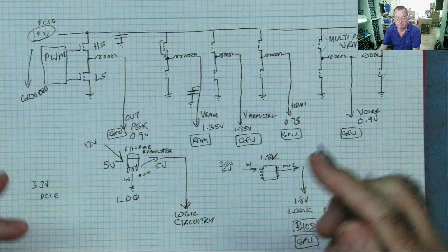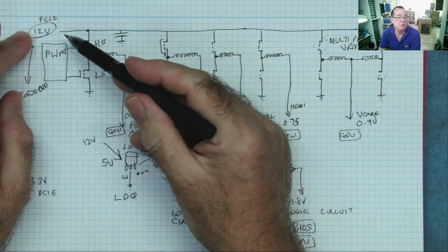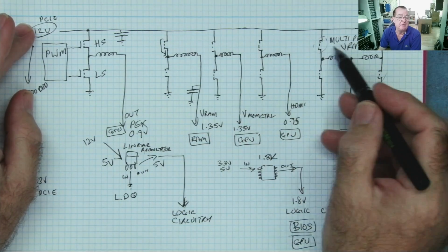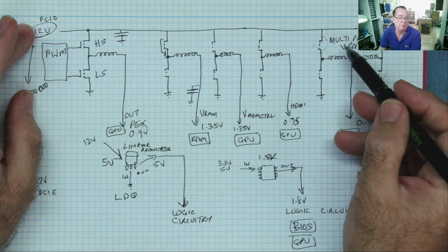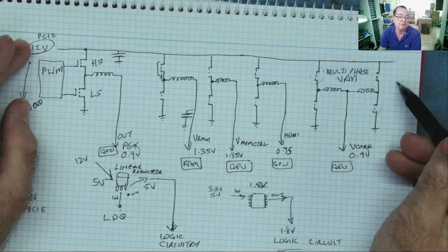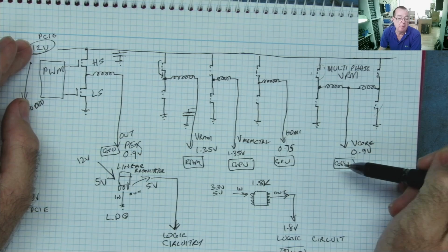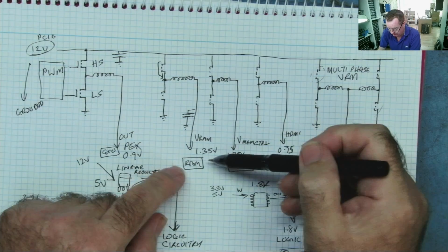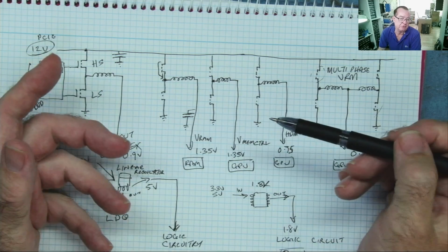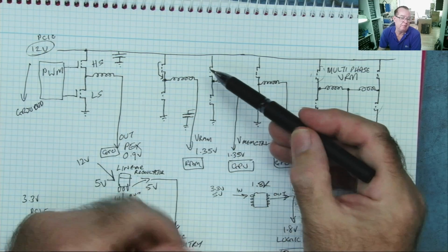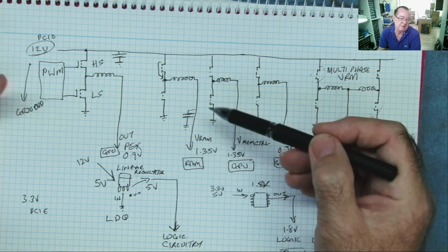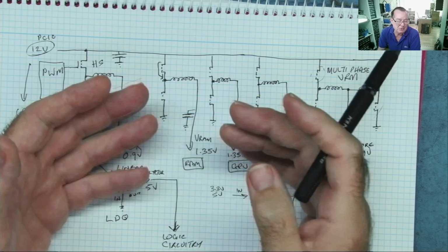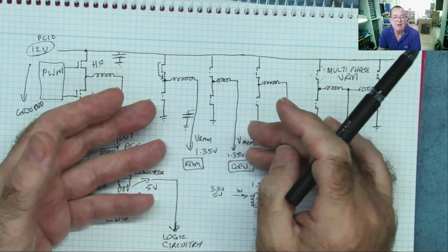Okay, so if we see a short from here, then we're going to have at least one of these short on one regulator, and there may be multiples on the same regulator, and we're probably going to have a short on whatever's being powered. Why? Because this RAM wants 1.35 volts. When this went short for an instant until maybe the fuse blew or something else gave up, it's now got 12 volts. It doesn't like it. It doesn't like 12 volts, even for milliseconds, yeah?